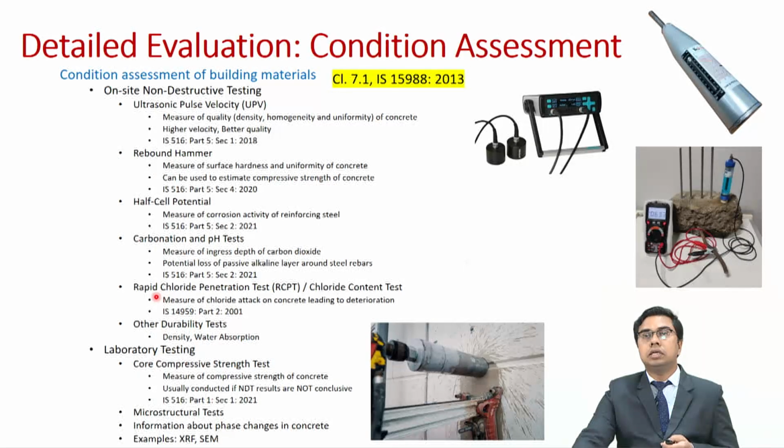You can also conduct the RCPT test, or rapid chloride penetration test, which gives a measure of chloride attack on concrete leading to deterioration. More details are available in IS 14959 part 2, 2001. You can also conduct other durability tests such as density, water absorption, water permeability, and so on.